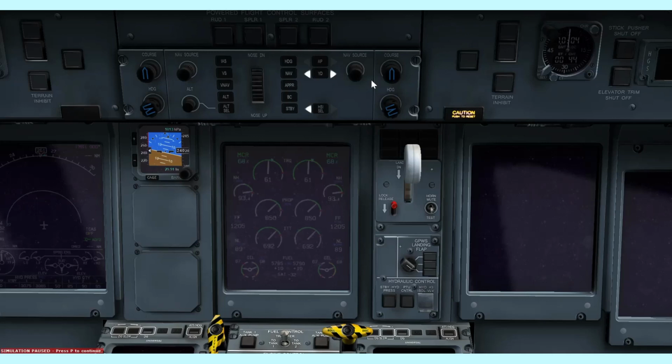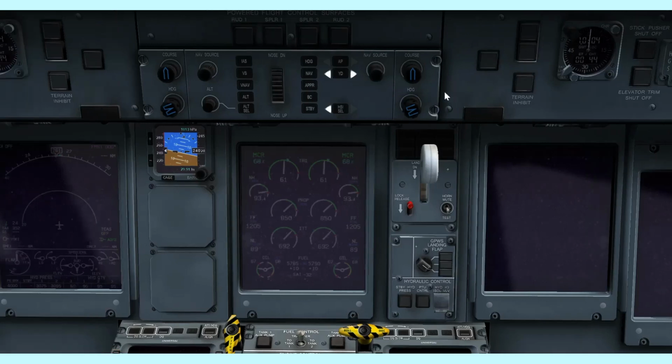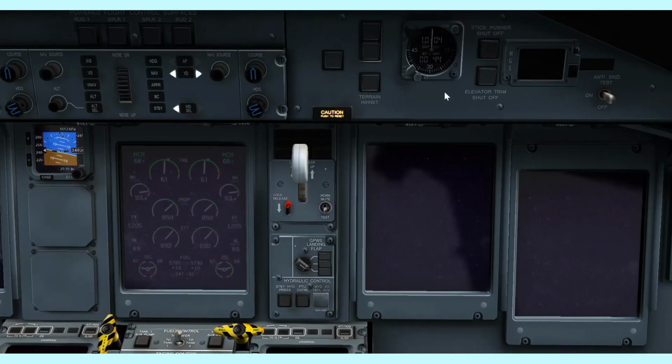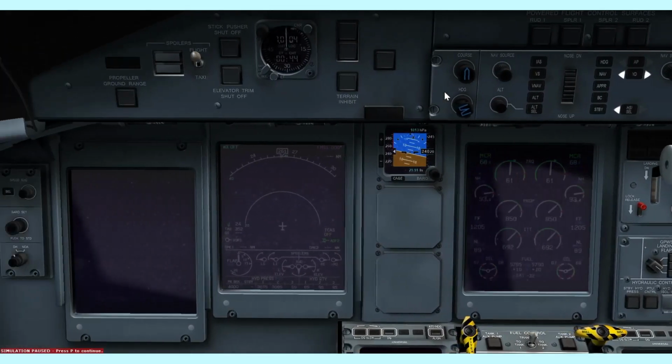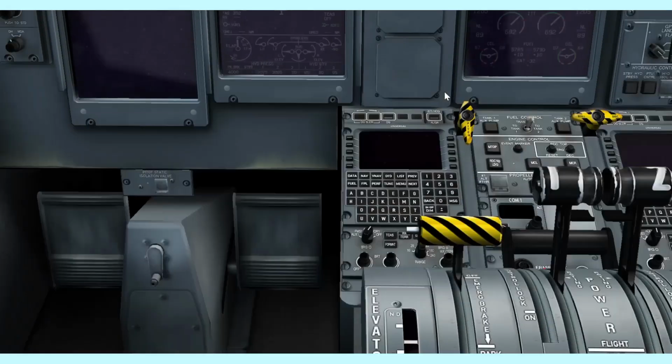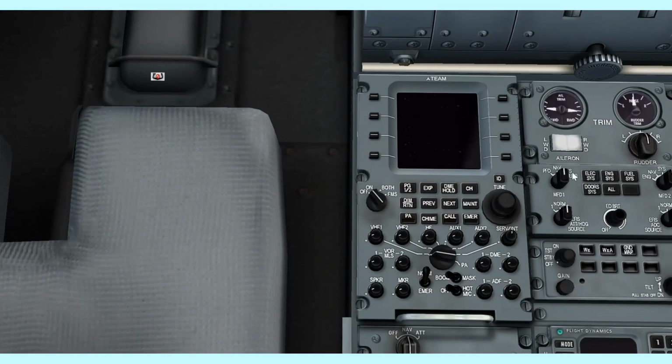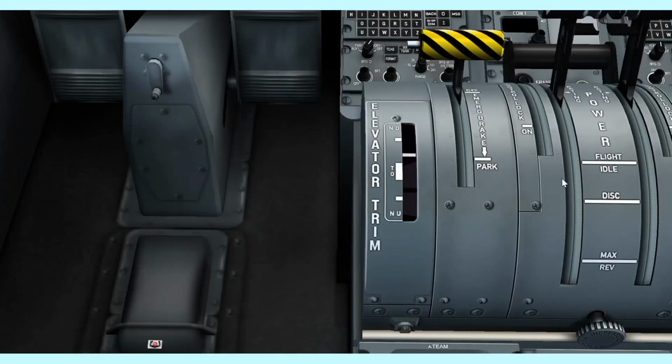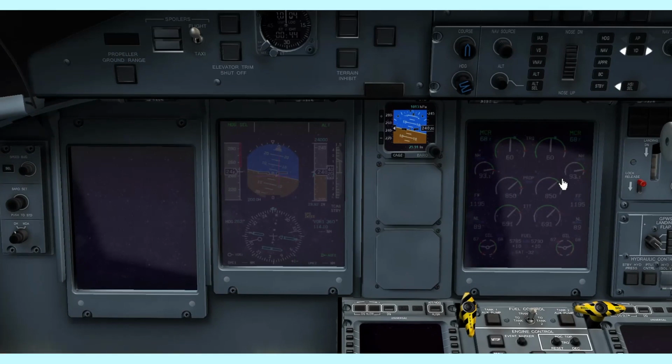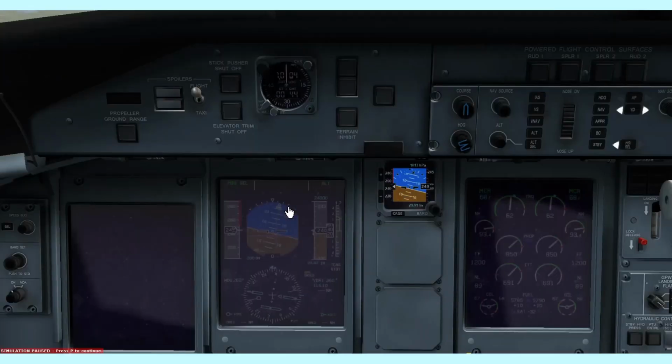So you do know that we do have some sort of glitches here and there. And all these displays on the first officer's side have also gone blank, and we don't have any displays. So in this case, when this sort of thing happens, you go to the MFD selector on the number 1 side and switch it to PFD. When you do that, you bring the PFD indication onto your MFD. So it's only the left hand seat pilot who will be able to control the aircraft in this case, and of course it should light up, and we don't want to be going out of control here.